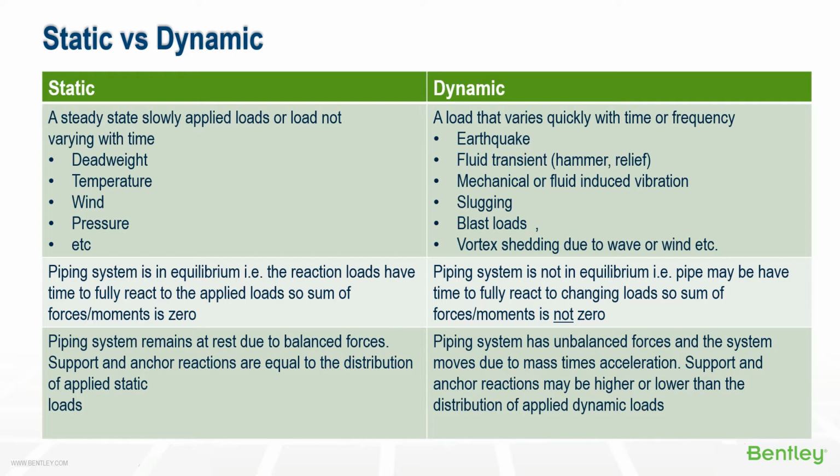These effects are considered to be nonlinear because the response of the support may change depending on the load. For example, a typical one-way restraint will prohibit pipe movement in the downward direction, whereas it offers no resistance to upward movement. Similarly, a support with a gap might not offer any resistance if the load is small. But if the load is large, the movement might be restricted by gap closure. Gaps and one-way restraints allow the designer to take advantage of the fact that these supports allow some or unrestricted